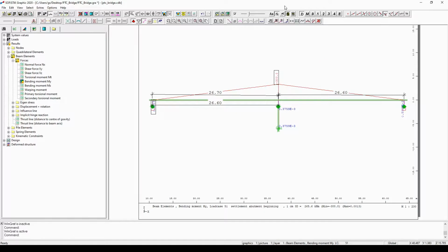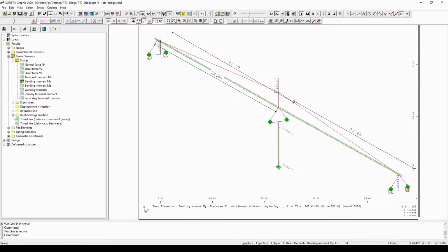Maybe it is also worth showing to you that if I select the perspective view now, the dimension lines that I have entered keep their original value, since I have defined them in the XZ or YZ or XY plane. So what I would like to say is that you should always define the dimension lines in one of the planes, but not in the three-dimensional system view. Because if you define a dimension line in the three-dimensional system view, it might not keep the original value when you change this 3D perspective.